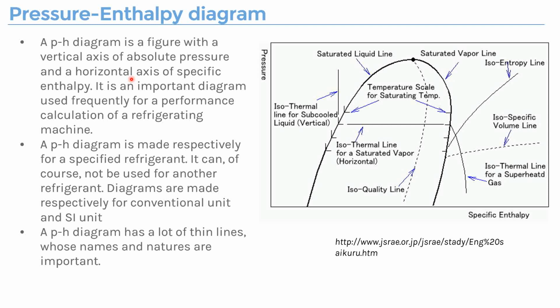But because this is for the previous several weeks, maybe, in the test, you need to get yourself very clear about which line represents these physics. For example, currently we have the pH diagram, which is pressure and enthalpy. So this curve separates the subcooled liquid and the saturated liquid on this curve, and on the other side is superheated. And if you draw a horizontal line, that's constant pressure, but the constant temperature would be like a vertical line first, horizontal, and go to the superheated part.